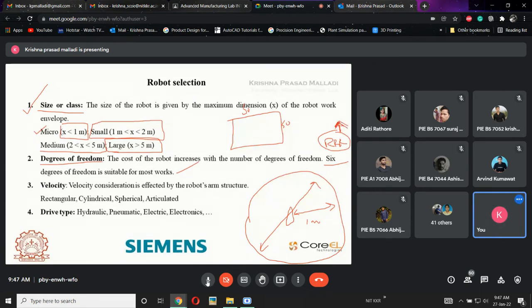Now what will happen if my robot needs to do some additional application? Then I will go for the Puma or Scara based upon the application. Generally these will have 6 degrees of freedom. If I want additional degrees of freedom, then I purchase the articulate robot and additionally add some conveyor or belt or something, to define extra motion, based upon the movement. So we are going to consider what type of robot I need to use, whether I am going to use 6 degrees of freedom.